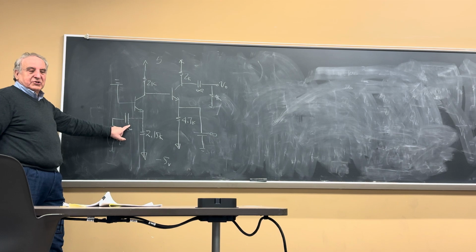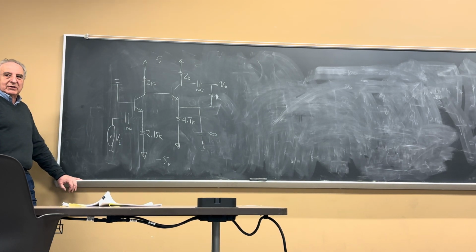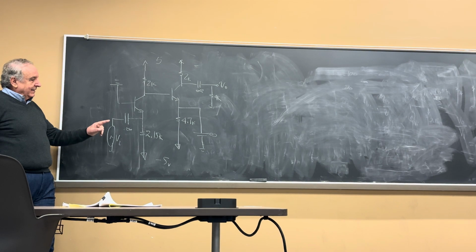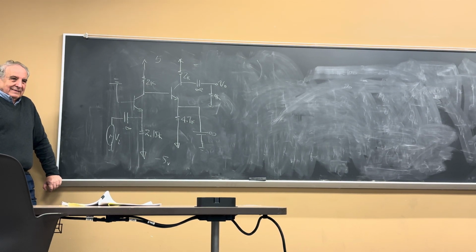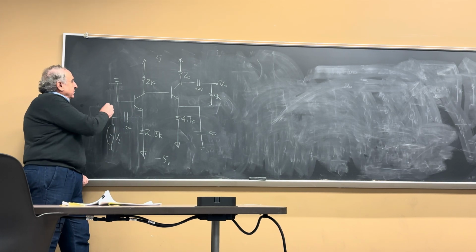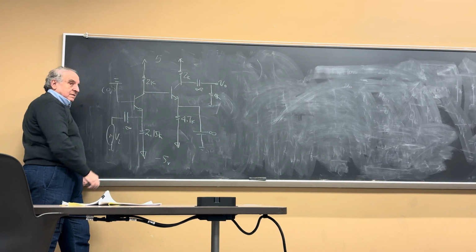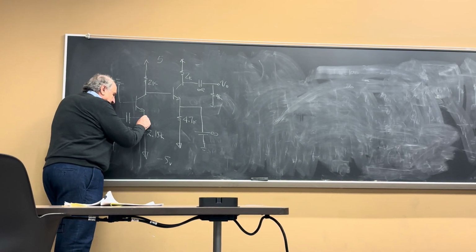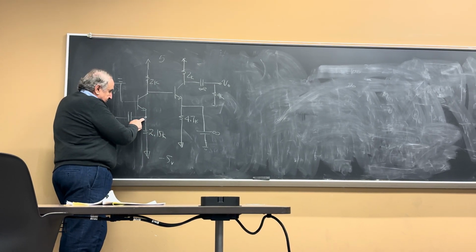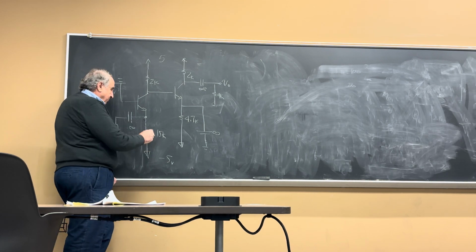The input transistor is what configuration? Common base, common emitter, common collector. Common base, right? Yeah. The base is common, it's ground. How about the output? Common emitter. Okay. Let's start here. What's this voltage? Right? What's this voltage? DC now. I say ignore base currents like I did in the quiz. What's this voltage? Minus 0.7.